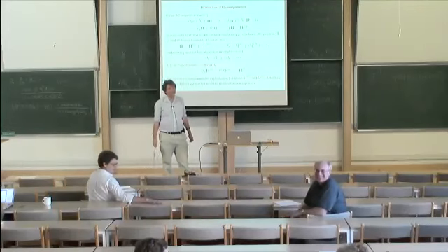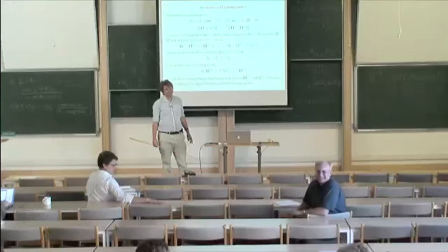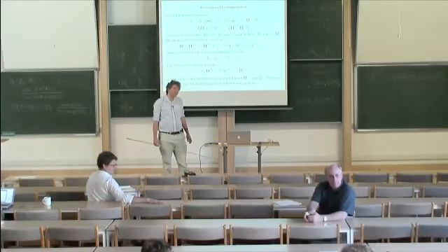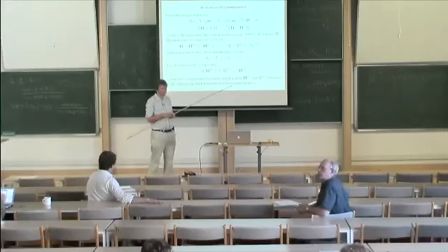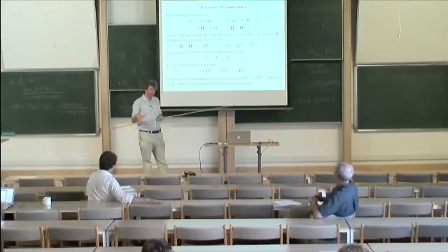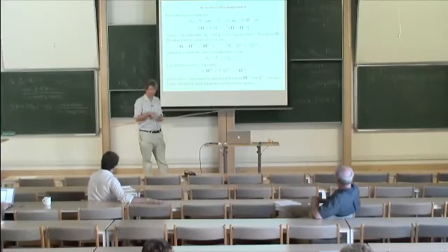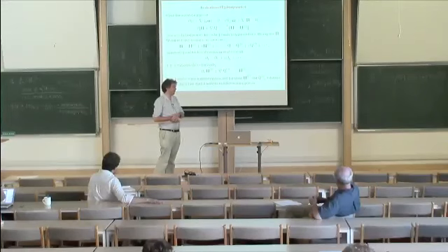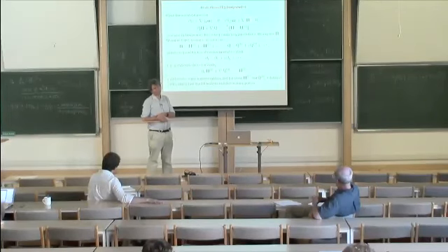But that makes me worry suddenly. You've got a finite velocity, anything you move at in the grid. Particles can only move at a certain velocity on the grid. Yes. That's not a velocity relative to the flow velocity. No, it's absolutely not like doing Grad 13 moment, where you expand around in the frame of the local fluid velocity. This is all in some absolute frame. Yeah, but doesn't this mean that you can't have a flow that's bigger than Mach 1? Because none of your particles go faster.